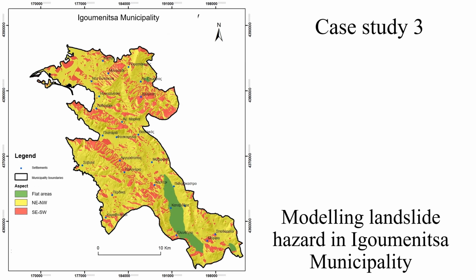We also used the slope aspect. In this part of western Greece, the wind and the weather phenomena are usually from the north. Therefore, slopes trending northwards, northeastwards and northwestwards are more susceptible to landslides. What is more, these slopes are not exposed to the sun.